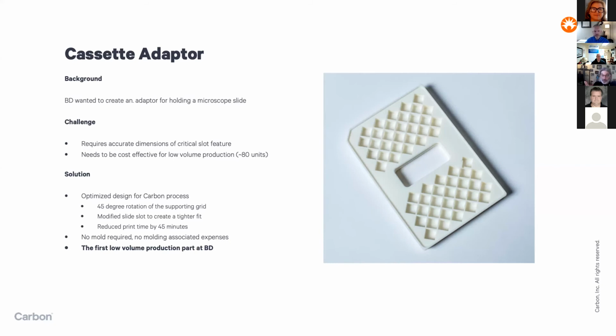Well, the operator looked at the geometry and just had one simple question. The back that you see in the diamond pattern in the traditional part was actually squares. So they were clocked 45 degrees into a square pattern. To print that one-to-one in Carbon, it was possible. However, all of those squares would have needed to be supported and then hand labor to remove them. By asking a simple question, and what I've started saying the acronym MFP, which I call Modify for Printability, rather than redesign: can we clock those squares 45 degrees and turn them into a diamond?